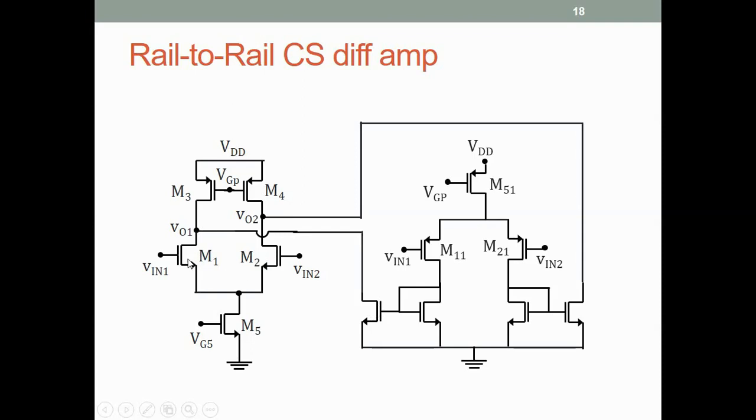So I have this current and I have this current, and if I connect the drains of the two transistors together, and I have a transistor above, then the transistor above will carry the sum of the currents in the transistors below. So adding currents is kind of trivial in transistor circuits. Adding voltages is not trivial; it actually requires summing amplifiers. Alright, so that is that.